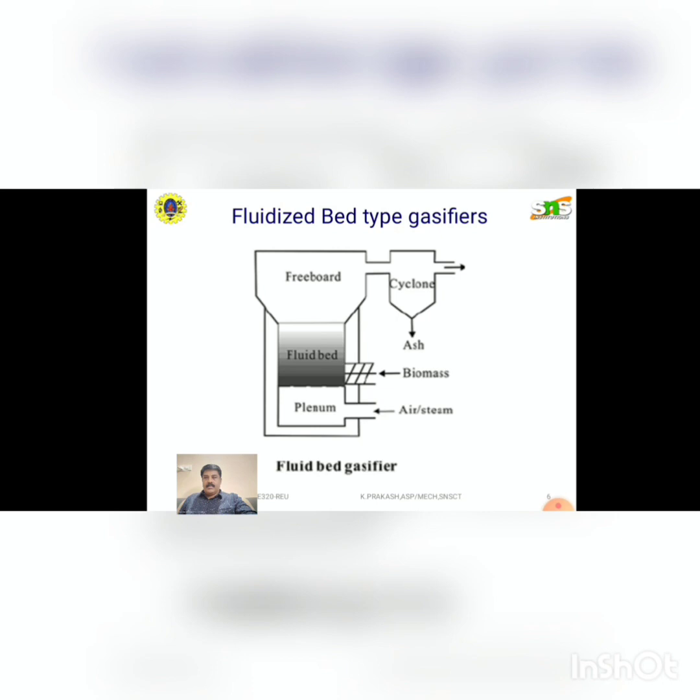The high surface area available in the fluidized bed and the constantly moving mass results in good conversion efficiency and lower operating temperature compared to fixed beds. The fluidized bed design produces a gas with low tar content but a high value of particulate. The high exit temperature complicates the efficient energy